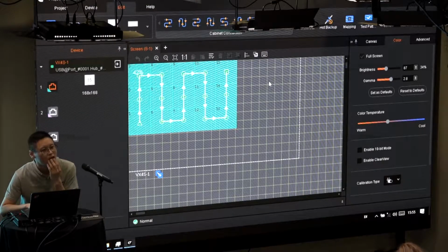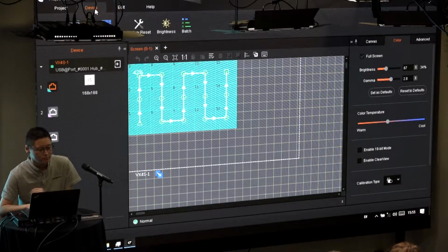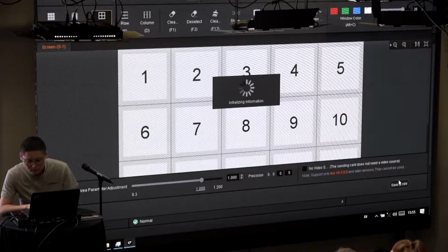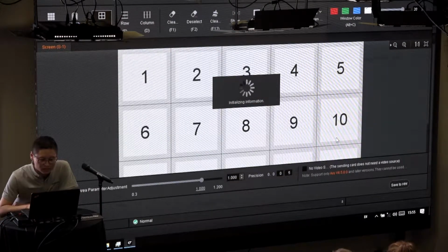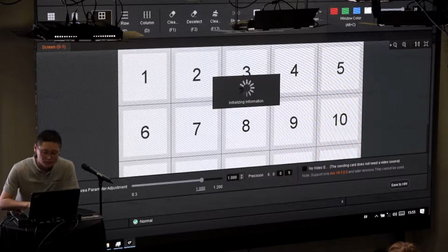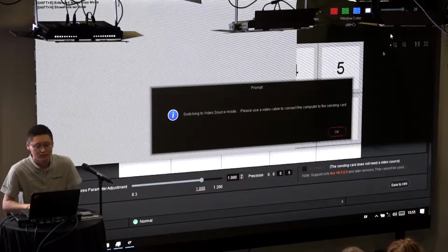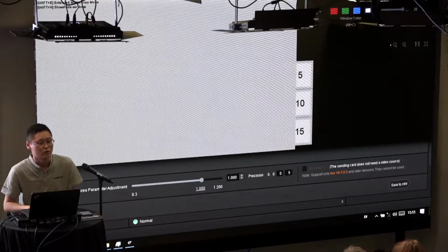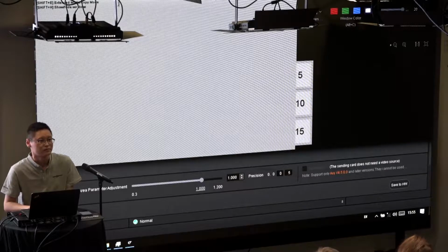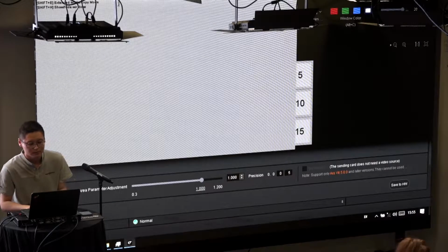Back to my question before, what about the scene, same here? If you just adjust the scene, brightness scene, you can't reset it on this software. Yes, on this software, you cannot do the recovery. The only way is go to the LCT and upload the coefficients again. So this software cannot recover what you just adjust on the lights. So you have to go back to LCT and upload the coefficients again. So is that a direct thing? Mhm.